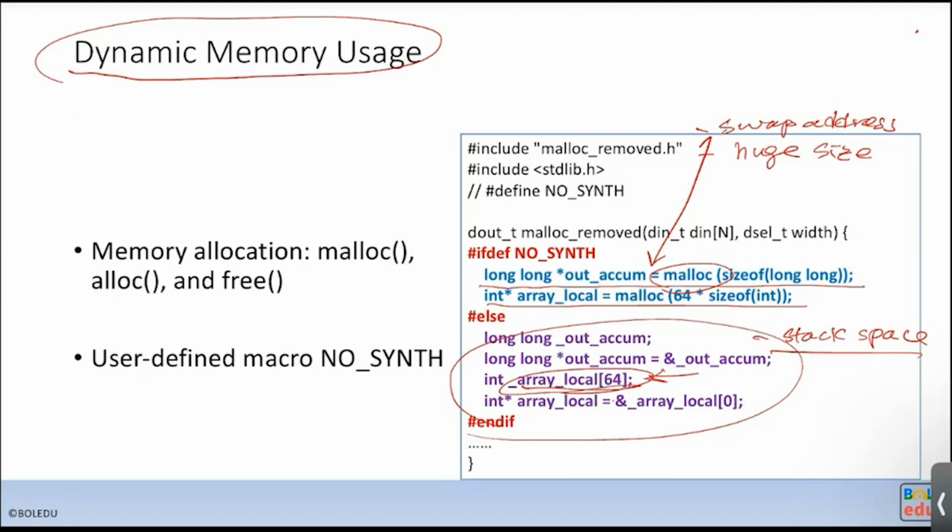So in this case, the standard or common practice is you define your own macro, let's say NO_SYNTHESIS. When you run the C simulation, you define NO_SYNTHESIS.